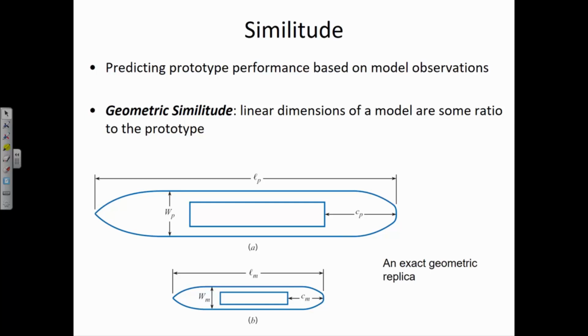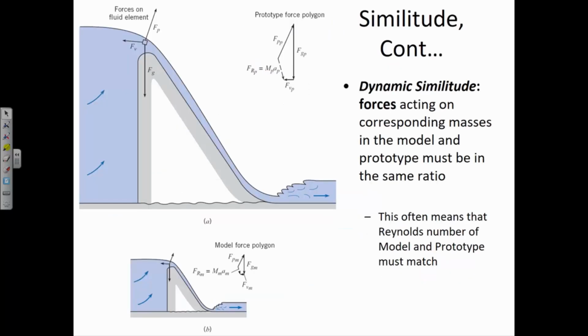But think about if you took an actual car to a similar height and dropped it. It's not going to do as well, right? And so it's really the forces that need to scale rather than the sizes. And so to simulate the behavior of an actual car by dropping a model, we'd have to maintain not geometric similitude, but we need to focus on dynamic similitude.